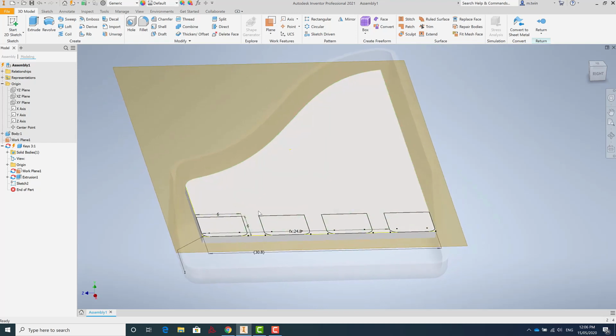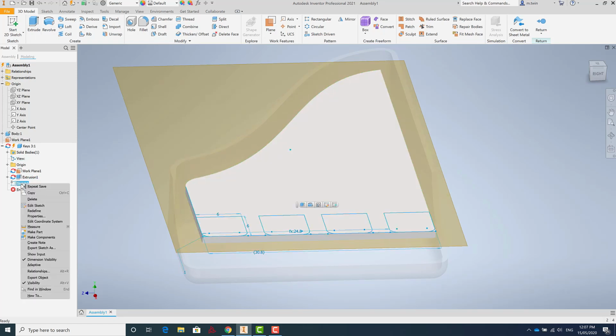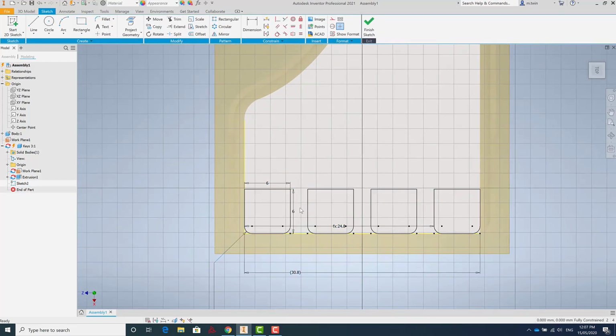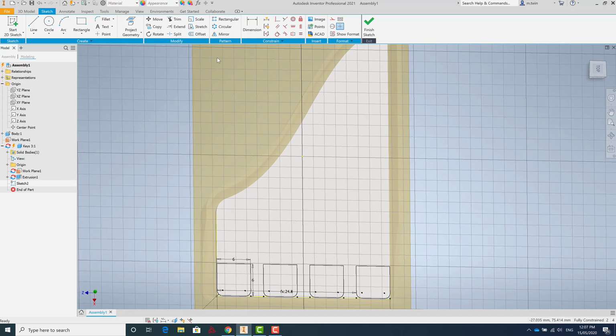We need to create the actual arms they'll sit on that'll vibrate and create the sound. So what we'll do is we need to again reference some geometry, and to that we'll go back into our sketch. So I'll go into here, we'll go edit sketch, and now we've got back to the same place we're on. We'll project our geometry here, and this time I want a decent offset from that geometry to give us a good rim to get that soundboard sort of effect happening. So we'll offset this by a pretty solid amount. I think I'll say in this case 3 millimeters.